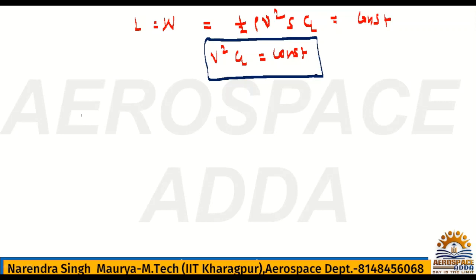So we take that two conditions, one at velocity at minimum power required and one is the normal speed. So because this product will be constant, then we can write V square CL is equal to, instead of this V, what we can write? We can write n times of Vmp square, instead of CL, what we can write? CL, which is at minimum power required. Agree? So now this is the formulation.